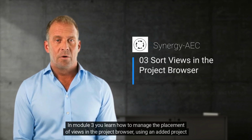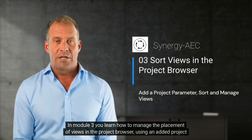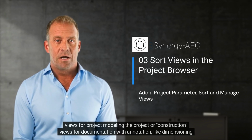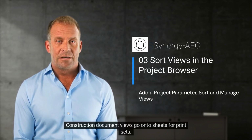In Module 3, you learn how to manage the placement of views in the project browser using an added project parameter. View categories could be for exports, rendering, presentations, or the most used designation as working views for project modeling, the project or construction views for documentation with annotation like dimensioning and tags. Construction document views go onto sheets for print sets.